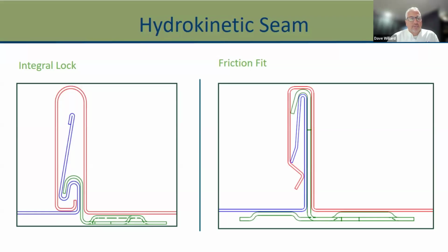Now with both of these, they're usually pinned at the ridge, and then the panel is allowed to expand and contract toward the eave of the panel. So that's kind of just an example of how those clips float. So the clip is attached and the panels just kind of float, and they're allowed to expand and contract up and down the building, which accommodates for long panel runs, 40, 50, 60 feet long. I mean, we've run panels as long as 90 feet.